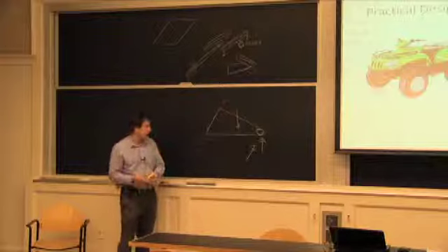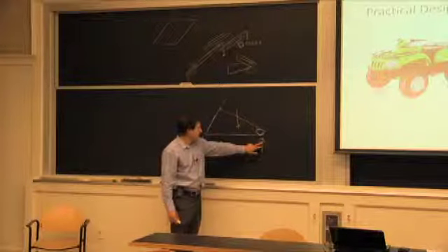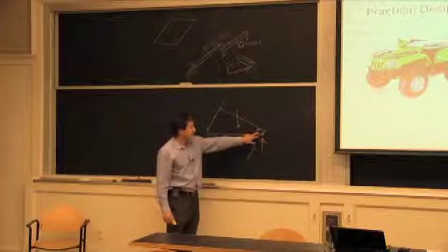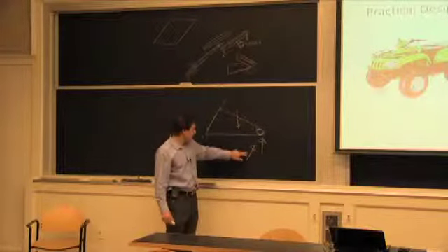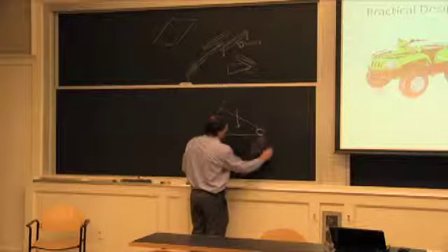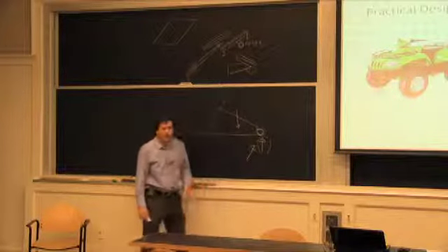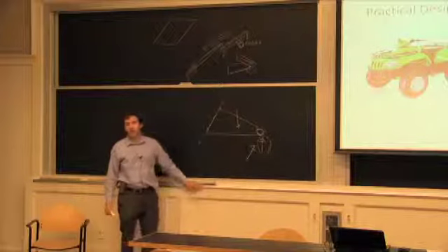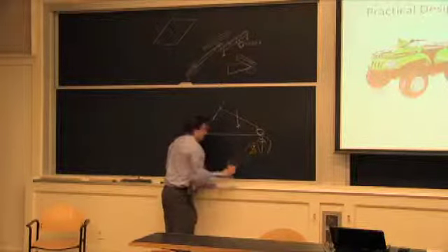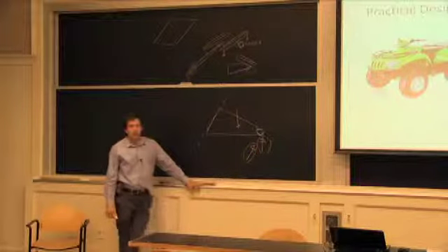There's only so much worst case forces that you can think of here for vertical load on that ball joint. And same for applying the brakes. If you arrive to a certain force for this, then what you need is a friction factor against the ground. And that will give you a good idea for this load going backward.